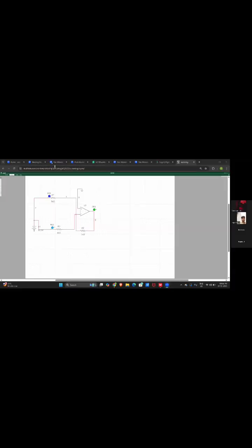Hello everyone. Myself Jagadish. I am concluding about the op-amp and its circuit application. This kind of configuration is frequently used in analog sensor signal conditioning, where interference must be rejected, and in audio electronics to eliminate hum and noise picked up by cables. It is also used in data acquisition systems requiring precise amplification of small differential signals while ignoring noise.